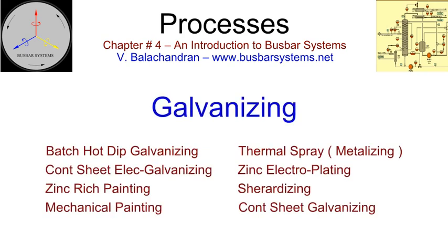Galvanizing. Galvanizing has been the most popular method of protection of steel against corrosion. Over a period, it has come to define the deposition of zinc over steel. The galvanizing process does not alter the mechanical properties of most of the structural steel, which is normally hot-rolled. The reduction in strength of a few parameters, even on cold-worked components, is minimal.